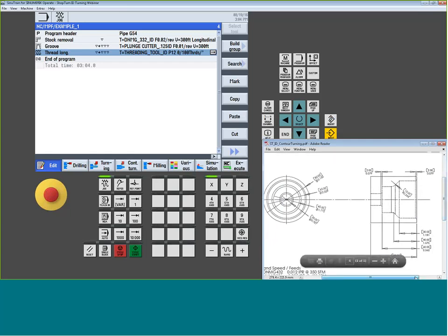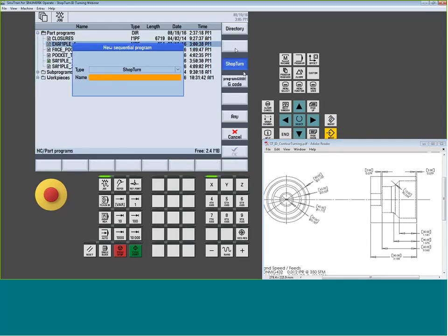So there we go. So we're going to have a little regular shaped bore. The part's going to start out, in this example, at 3.150 as the rough stock. We're going to assume that this has been pre-machined as a blank. I'm not going to worry about facing it. I'm just going to come in, generate the chamfer, create the bore, create the shape, and finish up our part.